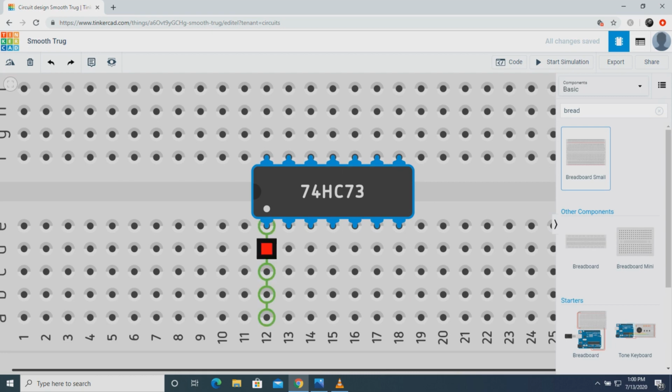And you don't need to look at the pin diagrams because they have named it. This is the clock for the first JK flip-flop, then this is the reset button, this is K, okay, and that is the power port. There is another clock, another reset, another J2, this is the inverted output, Q prime output, so K2, ground, output. And if you just put your mouse there, you will get these names, right?